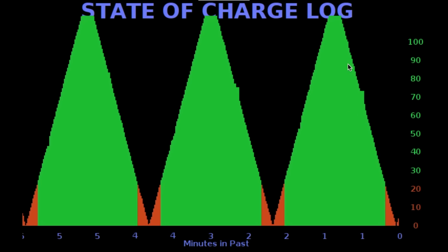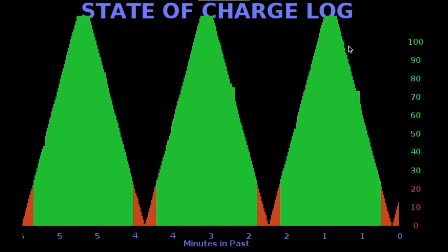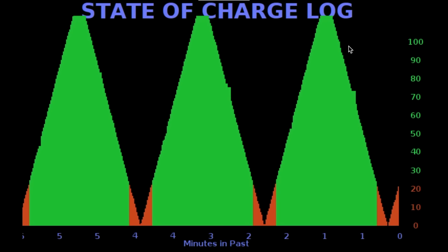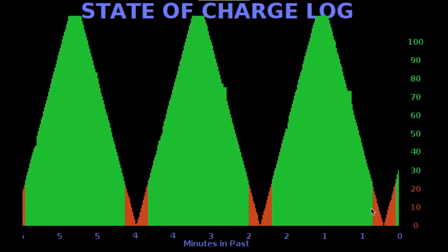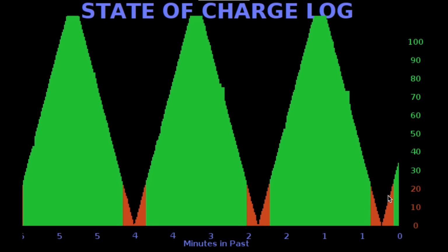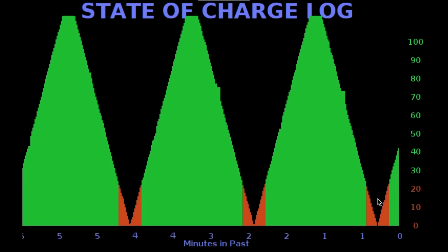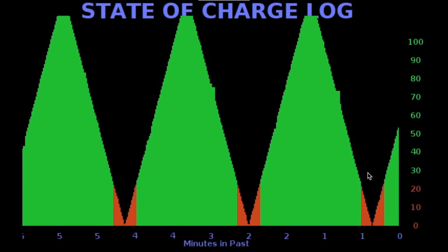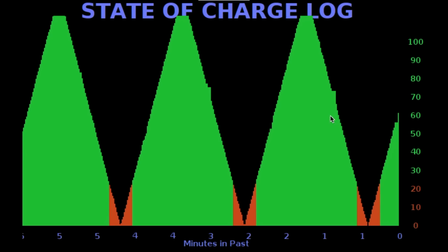So you don't want to see it going to 100% during the day and cutting off your solar panels to keep from overcharging the batteries. And you certainly don't want to shut down at night because your state of charge got too low and we had to shut off the battery and your power to prevent damage to the Tesla Model S modules.